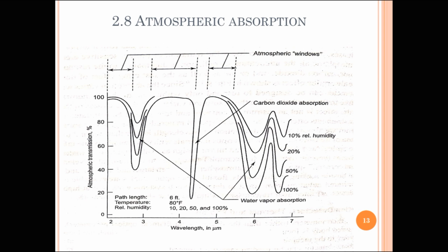In atmospheric air, the attenuation of radiation is due mainly to the resonance absorption bands of water vapor, carbon dioxide, and ozone, as well as the scattering effect of dust particles and water droplets. The absorption effect is shown in this figure. Since the absorption varies with the wavelength, a radiation thermometer can be designed to respond only within one of the windows shown, thus making it insensitive to these effects.